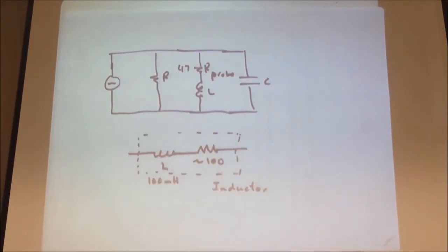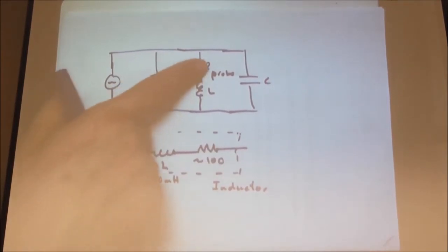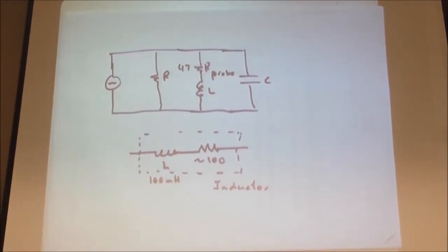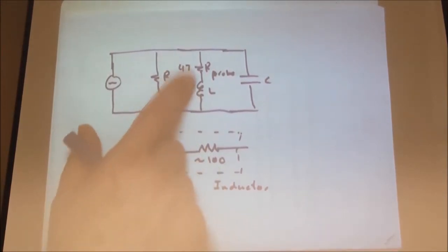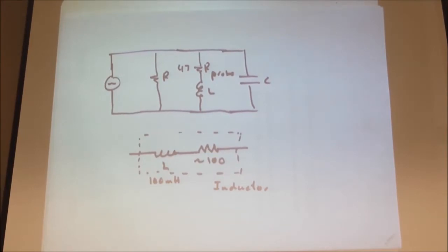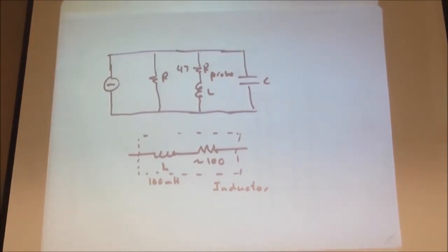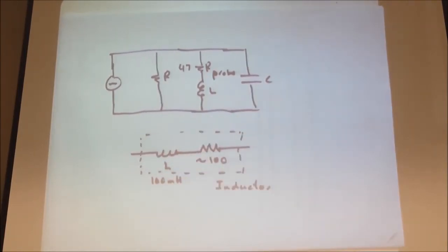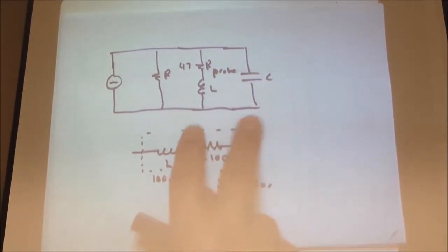So the circuit you modeled in PSpice was the ideal circuit without that guy. But the characteristic circuit that you implement physically has this resistance, and then we have this other resistance. And so the results are going to be a little bit different. Where they're going to play out is in the attenuation constant. The resonant frequency stays about the same, and it's dominant relative to the attenuation constant in this problem.